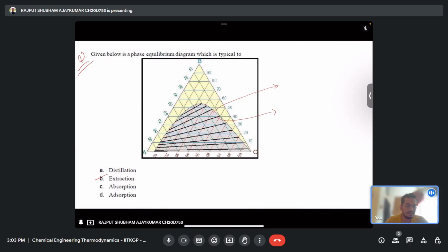Distillation is somewhat like what I have discussed: the distillation column can be split in different forms. For the simple distillation column, the feed will be at the center point of the column. The rectification section is at the top of the column, and the stripping section at the bottom. It's like rectifying the vapor component, so the vapor goes from the top to the condenser, and similarly from the bottom is the stripping of the less volatile components.